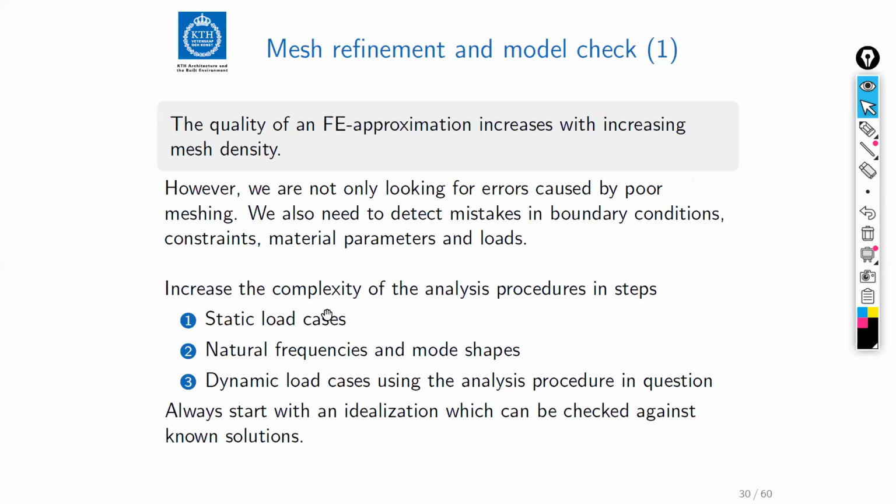So this is the way we increase the complexity in the modeling: by starting with a beam model, and then if we find that we need something more complex, we add complexity in steps. And every time we create a new model, we ask: does it work correctly with static loads? Do the natural frequencies and mode shapes seem all right? If so, yes, let's do the dynamic analysis and run the train or cars or wind load or whatever it was that we were looking for in the beginning.